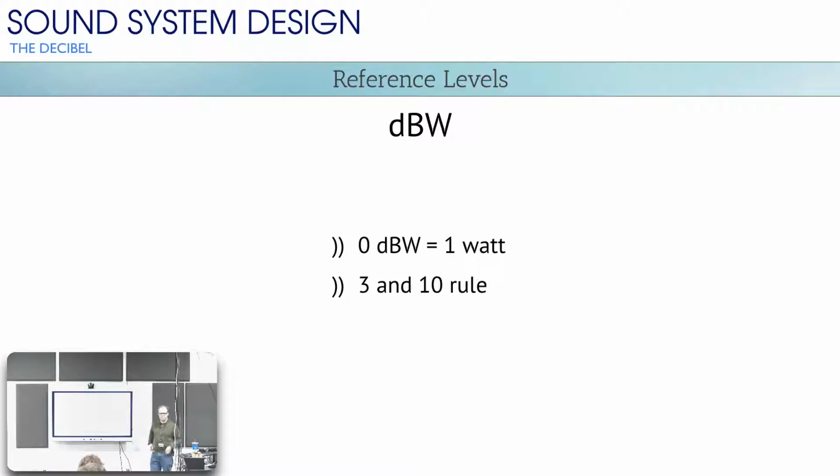I feel like our audio really uses that to their advantage. Oh yeah, a lot. That's really what they advertise. But think about it. 50 watts to 100 watts. What's the dB difference there? Let's assume that everything else about the two amplifiers is the same. What is the difference going to be in sound output between those two amps? 3 dB, which you can barely hear.